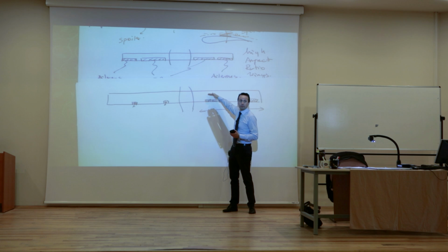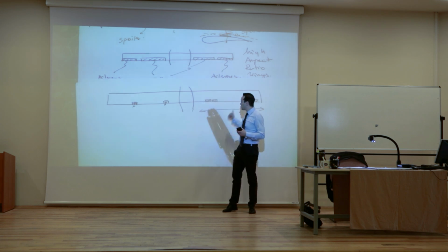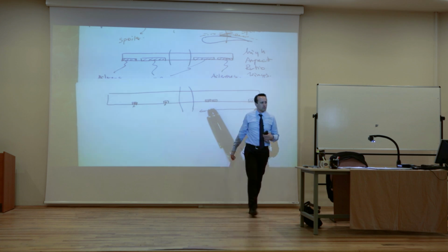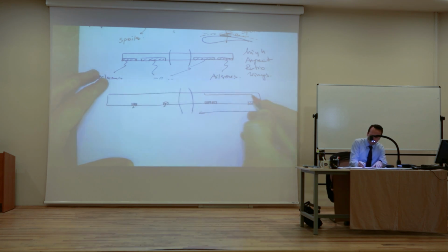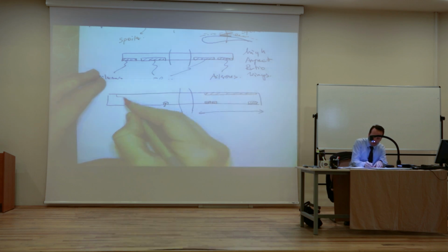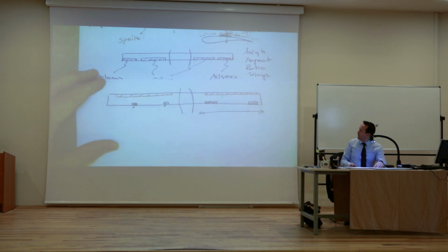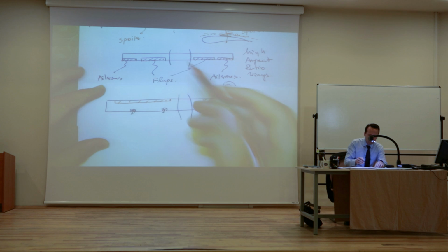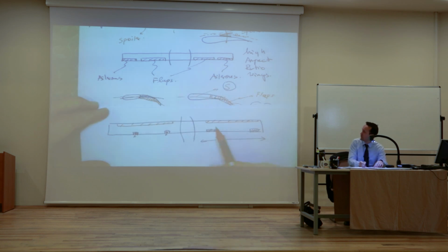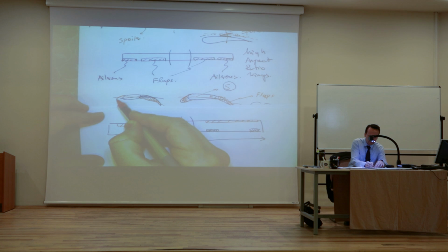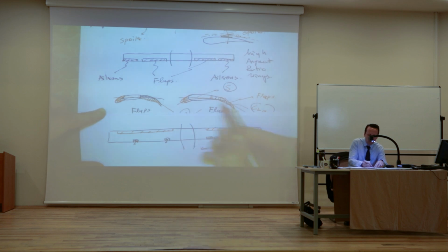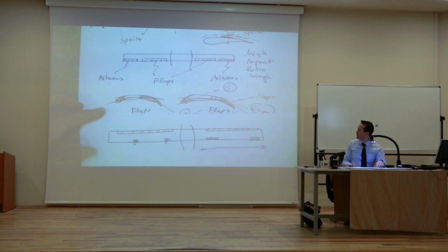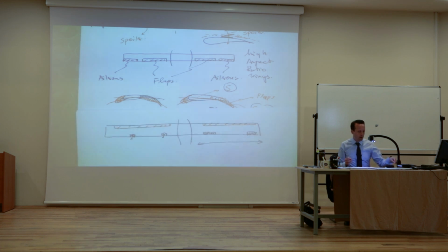So if you look at the wing, you see a lot of stuff. You see the flaps, you see the spoilers, you see the ailerons. You know, it's kind of crowded there. And sometimes, one more thing, you might have pieces in the front. They are very similar to the ailerons. Not ailerons, I'm sorry. They are similar to the flaps. They just go to the front and they actually do that. And they are actually increasing this even further, the CL alpha. Okay? So that's what's happening on the wings.